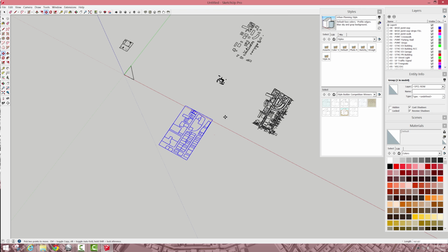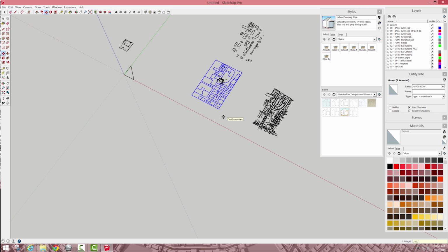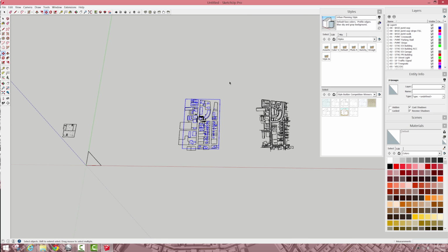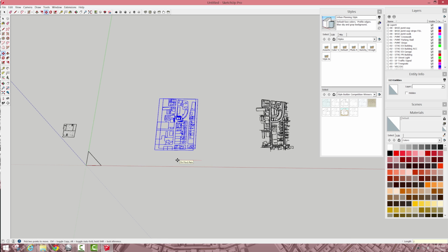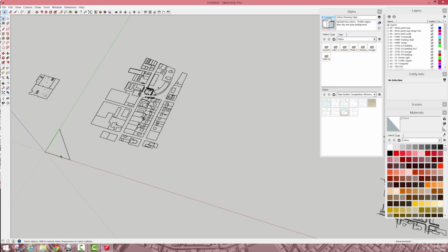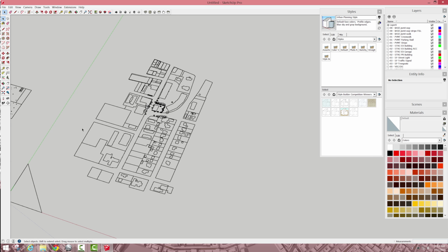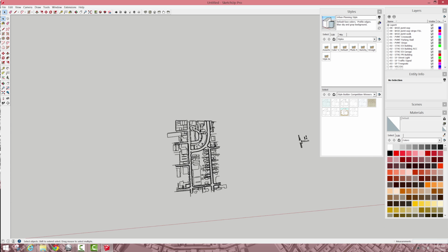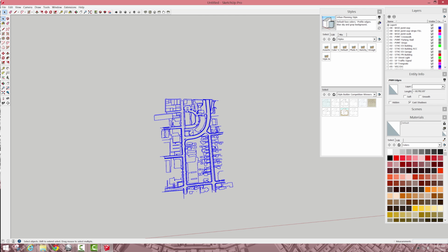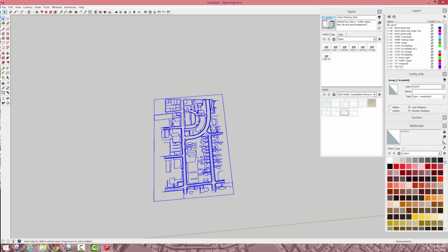These are known numbers. So like I knew I set this by 2500. This one was also 2500, and then back to where it's drawn in AutoCAD is 2500. So now if I make any additions in CAD, these are all referenced to one another. It's close to 0, 0. So this isn't geolocated, but it is in a place that's consistent. So I know like if we make any changes, say we decide that we want the parking lot to be different, that'll be easy to just bring it over from the CAD work.